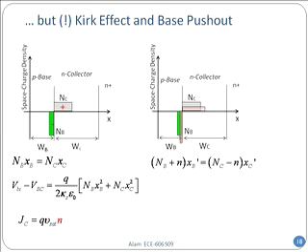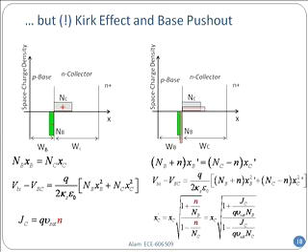Because of this change in the charge, the depletion region will also not remain the same. Xb prime now and Xc prime. You can again do Vbi minus Vbc because Vbc is your battery. That has not changed. Vbi is a material dependent thing. That has not changed. So now, when you solve these two pair of equations, what you will see is this. And this takes a few minutes, go home and do it.